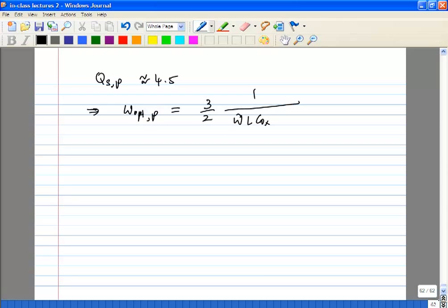This is omega C ox. So Cgs is 2/3, right? 2/3 W L C ox. And you put Qsp equals 4.5. Qsp is the power constrained Qs, so it is Qs after you have optimized Qs, after you have applied the power constraint.